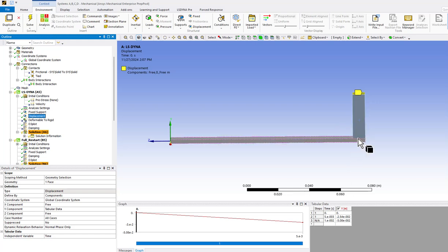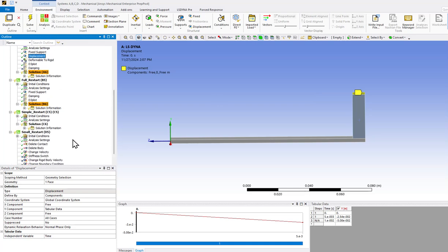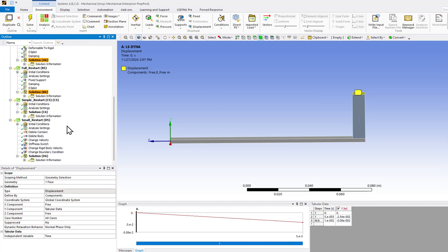So first step, I'm going to press it down, so you have a very simple bending problem. And in the second step, in a small restart, I'm going to delete this body, which, you can sort of imagine, is going to cause this board to rebound, right? Which is a way that I would like to use a very simple example to do a small restart.